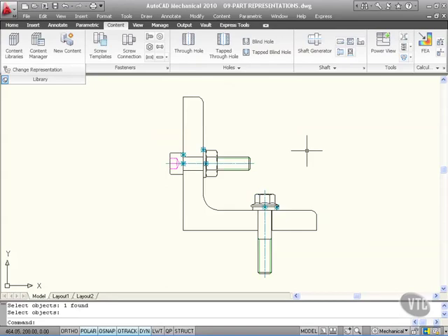What they allow you to do is show an object in a particular manner, whether that be symbolic, simplified or standard. Most of the time you will use standard like this for detailed drawing, but there will be occasions, manufacturing drawings and so on, where you only need to use the symbolic settings because the fitter or the manufacturer knows exactly what you're talking about anyway.